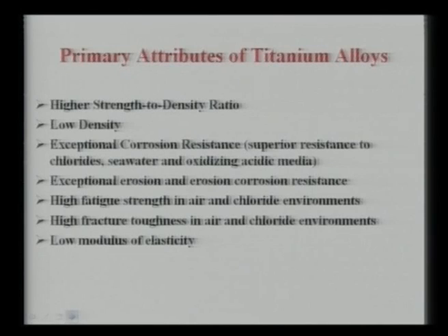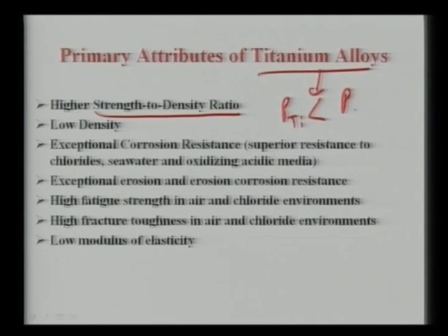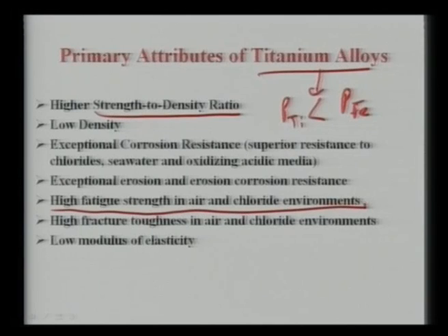Now coming to the titanium alloys. These titanium alloys have a very good strength to density ratio, because the density rho of titanium is much less than rho of iron or steel. So when you divide the strength by density, you get higher specific strength values for titanium. It has exceptional corrosion resistance, much better than that of steel materials. It has good fatigue strength, much better than steel, and it also has high fracture toughness in air or chloride environment.